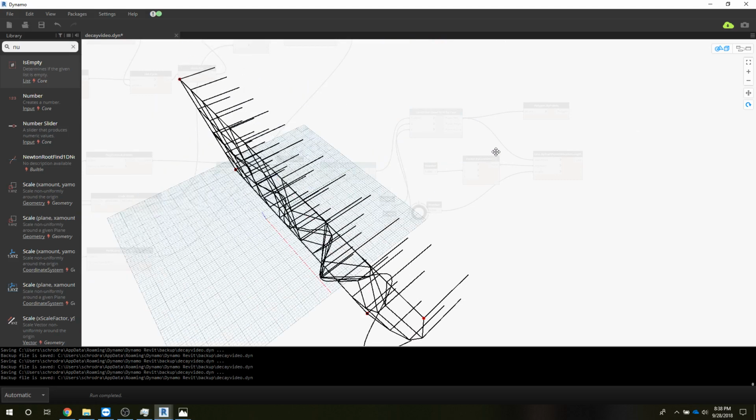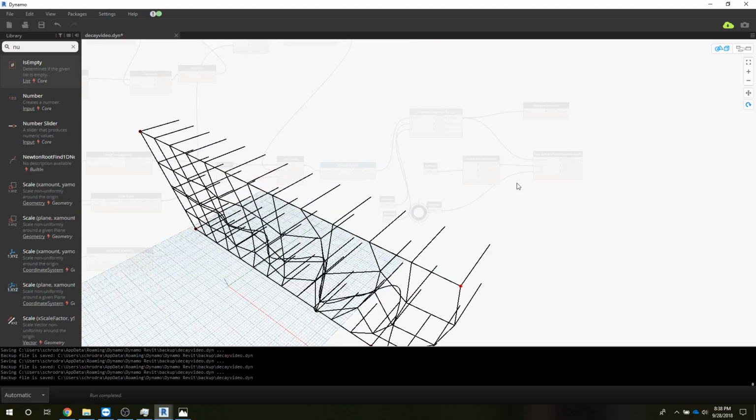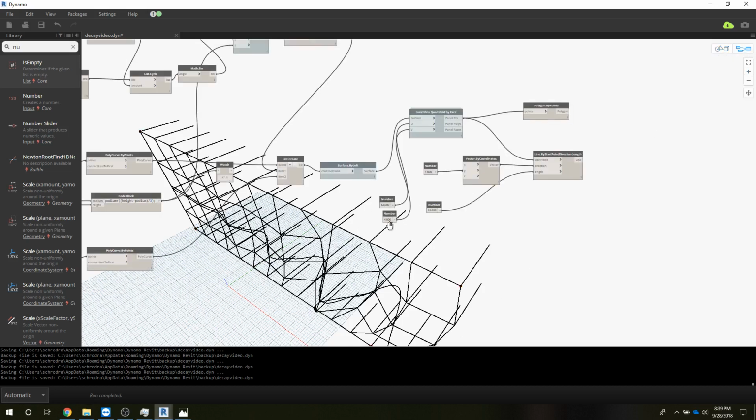And that's a problem when we want to try to align it to a planar surface, which might be the floors, interior of the building, or trusses. So our way to solve that problem then is to intersect it with another plane. In this case, a quick way to go about that idea would be to take the line that's at the top of our facade line and then extrude it down to make a surface, and then move that surface back to represent our wall surface.